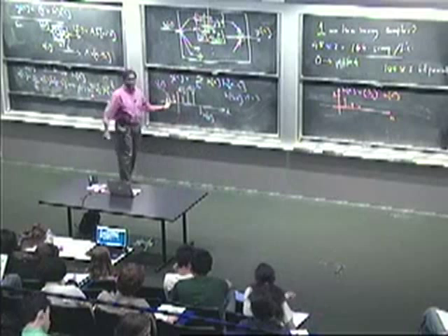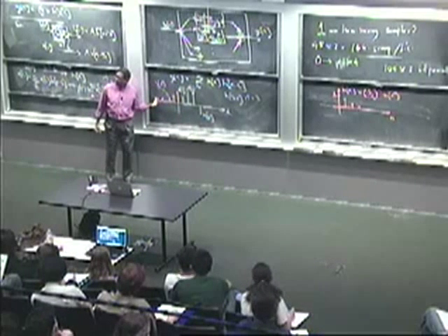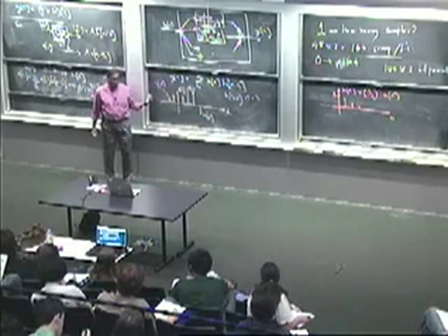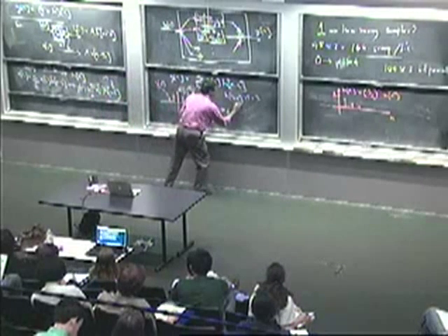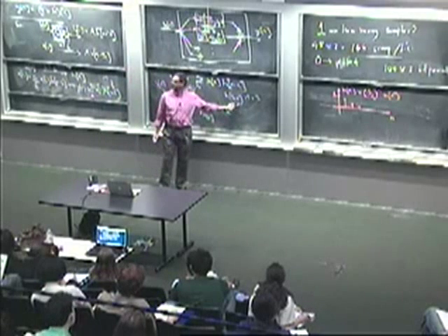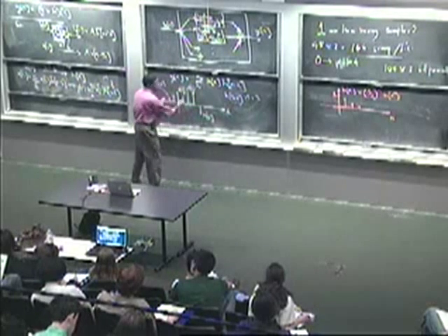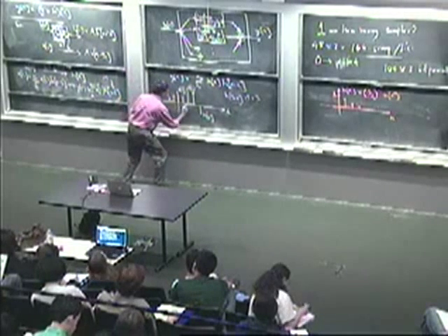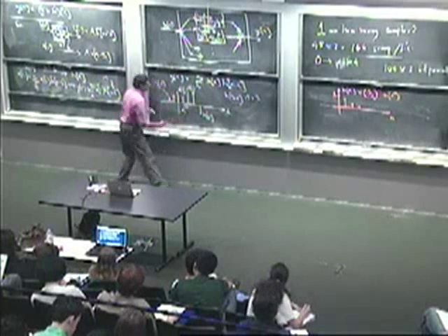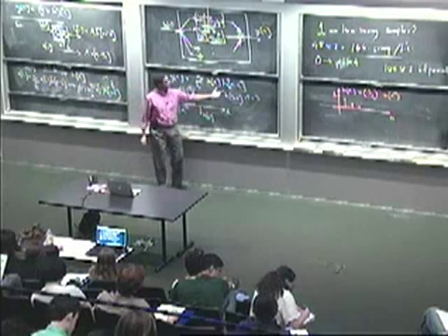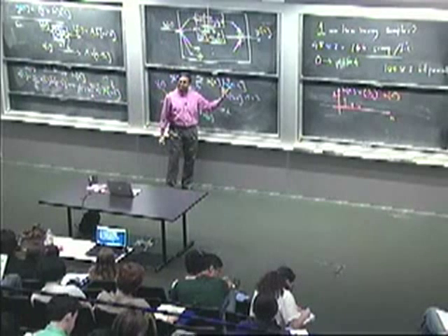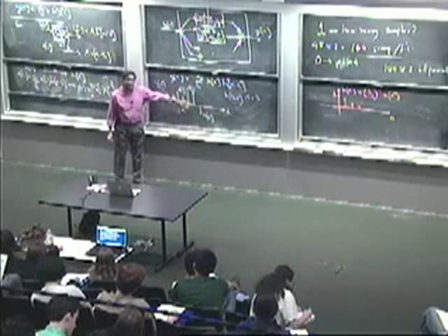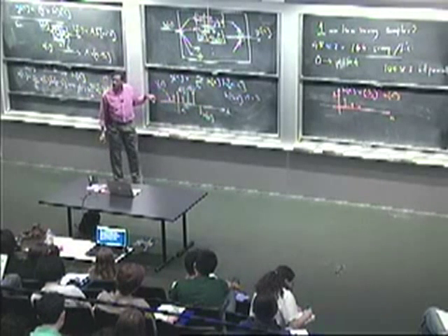So that corresponds to sliding this over. Do I slide it to the right by 3, to the left by 3? You can tell by looking at the argument here. Whatever used to happen at 0 has now got to happen at k equals 3. So that means a rightward shift. So you flip this over, and then you slide it by n steps. You take the h of k, flip it around to get h of minus k, slide it by n steps. If n is positive, you're sliding it to the right. If n is negative, you're sliding it to the left.